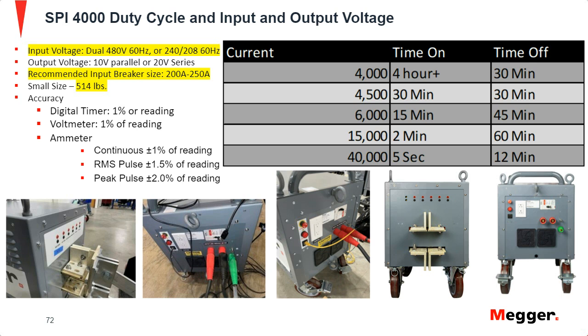Yeah, so this aligns with the previous question, and the answer is exactly what Dozy answered. Probably they are thinking about the timing test, which is usually done on medium voltage breakers or high voltage breakers. When we talk about primary injection testing, we are specifically talking about low voltage circuit breakers. And like Dozy mentioned, we are just looking for long time, short time, instantaneous, and ground fault testing on low voltage. The timing test the audience is referring to in this question is more related to medium voltage and high voltage breakers, which is a totally different part of testing.